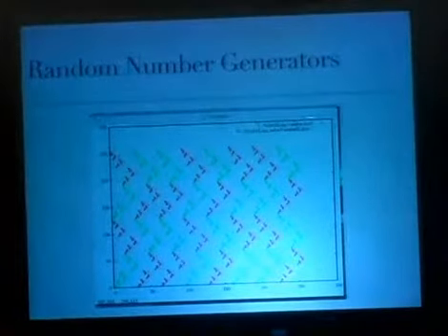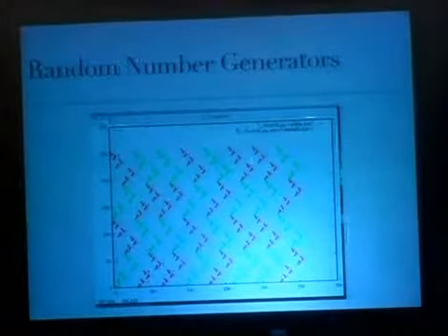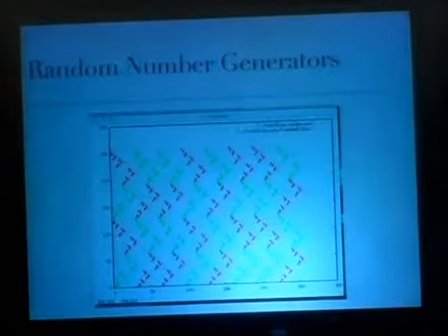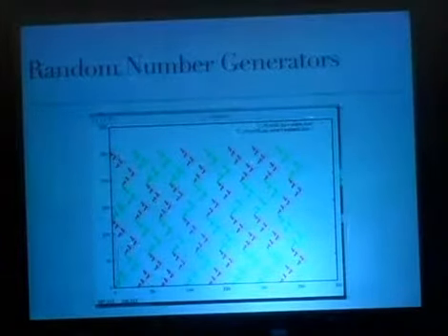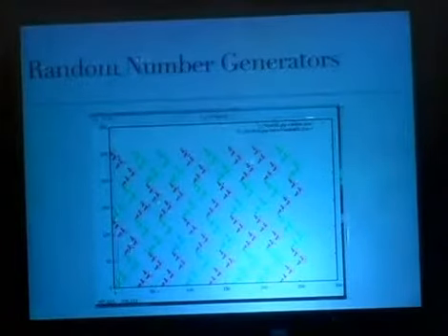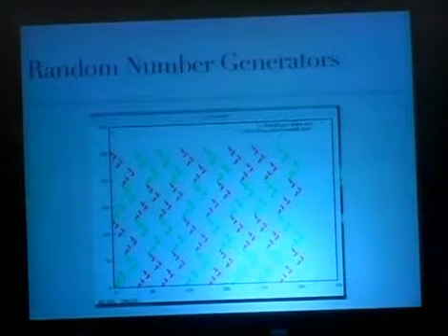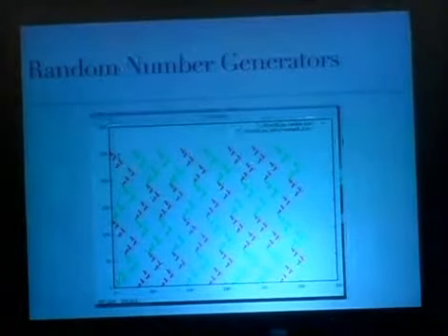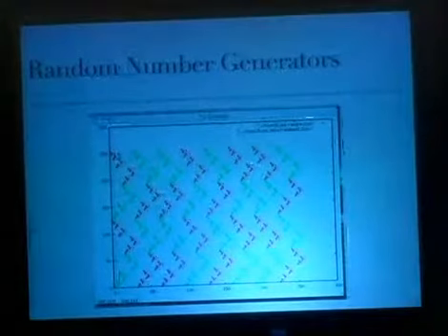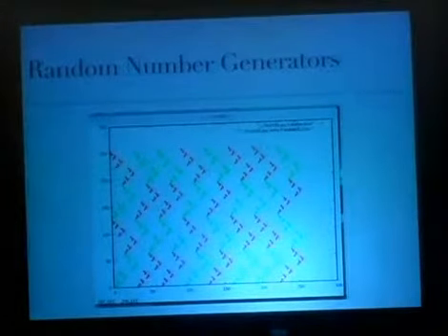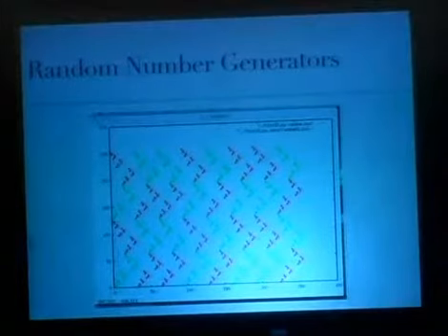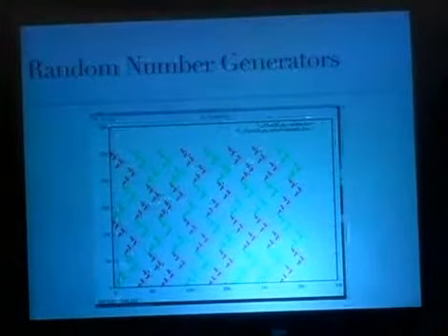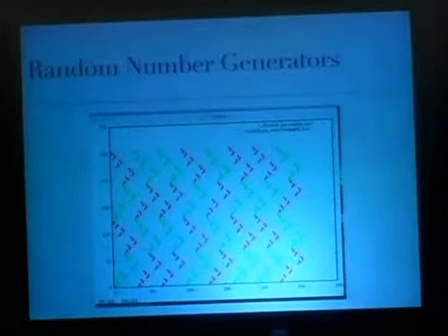Do these look random to anyone here? This is a snowflake pattern which is generated by a linear feedback shift register. This is one of the worst random number generators I've seen. The entire state of this is determined by a 16-bit register that's fed by real random hardware data. That's then shuffled around repeatedly to produce the same sequence of 65,000 samples. So if you plot the first byte that you get along with the second byte that you get in order continuously, you wind up with a snowflake pattern.